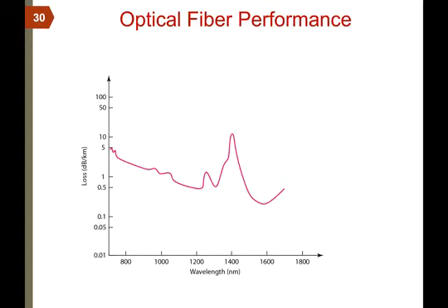If you look at the performance of the fiber optic, although we are dealing with light here, still, because the glass is not pure glass, there is also attenuation in this case. So when the cable length increases, of course the loss will increase. The loss is also affected by the wavelength of the light, in nanometers.